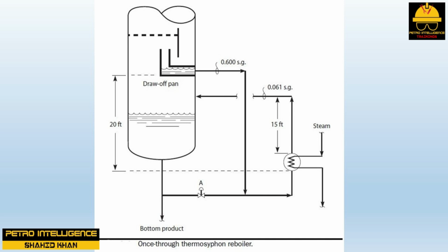Reboiler is partially plugged. Reboiler feed line is restricted. Reboiler design pressure drop is excessive. Tower bottom liquid level is covering the reboiler vapor return nozzle.